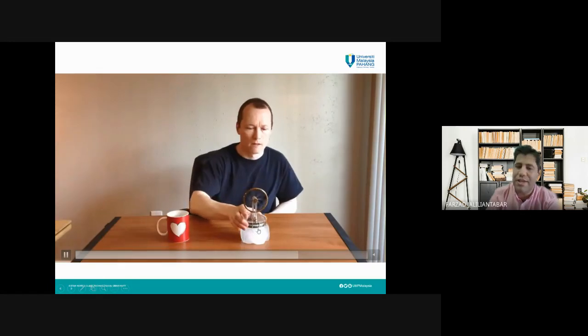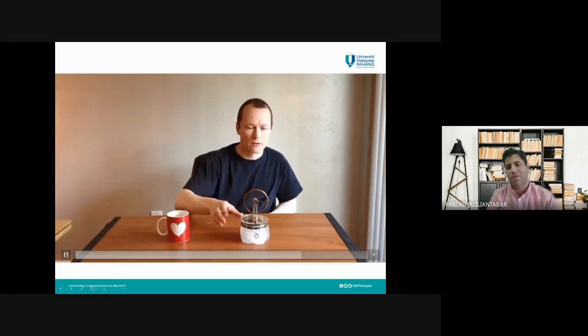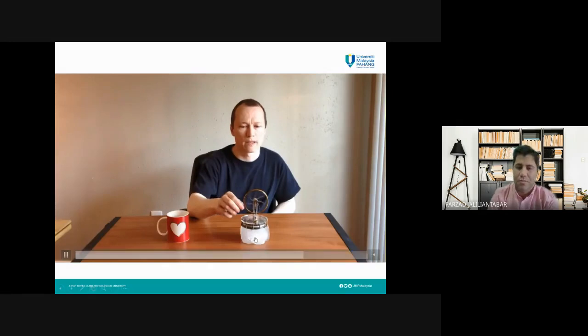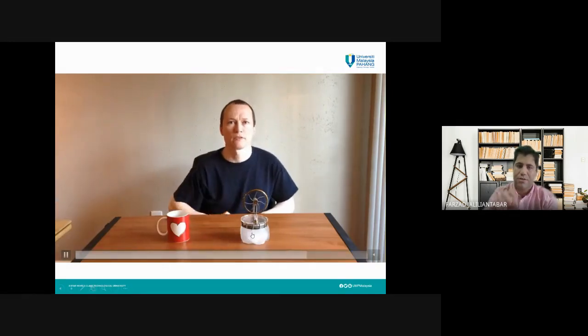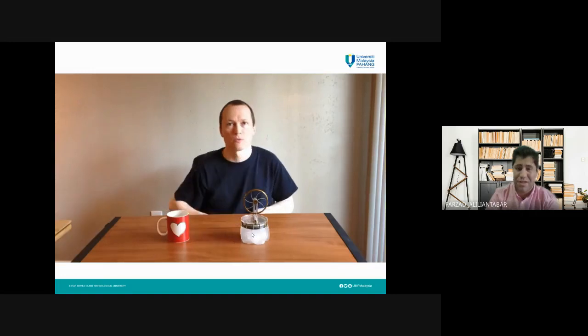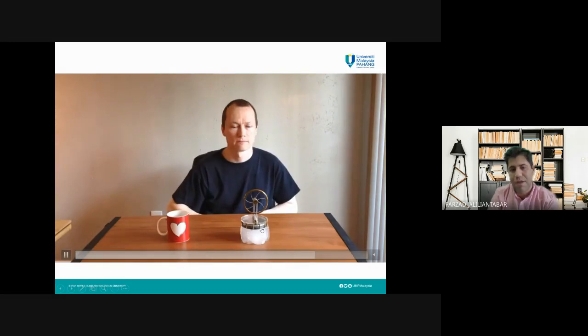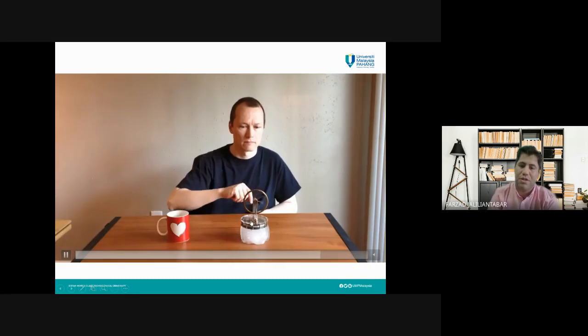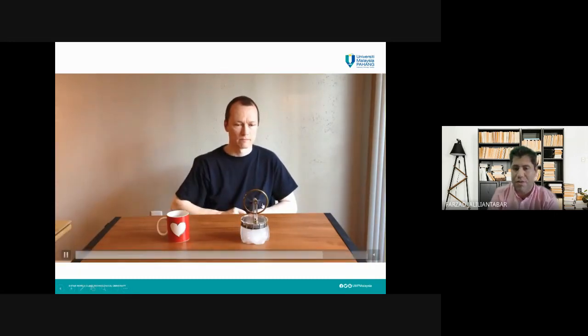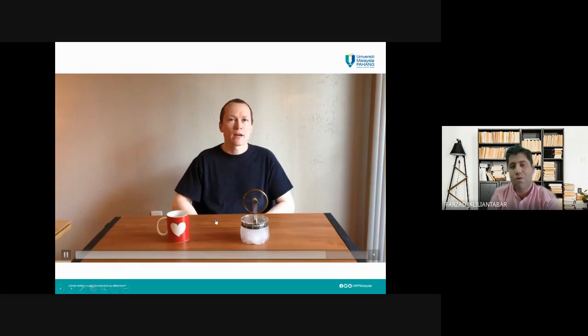We can also change the hot surface and cold surface. Here, when we put this Stirling engine on top of a piece of ice, you can see the cold surface will be the bottom surface, and the hot surface, the surface with higher temperature, is the top surface. So you can see here, again, this will work. We just need to have that temperature difference between two different surfaces of the piston cylinder in the Stirling engine to run this engine.